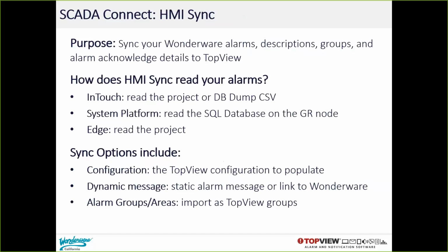The next step is to sync your Wonderware alarm to TopView. This step configures your alarms, alarm acknowledgements, alarm descriptions, and groups or areas for use by the TopView engine. The method used for syncing alarms depends on the Wonderware software. For InTouch, we can read the InTouch project or parse a dbdump CSV file. For System Platform, we read the alarms from the Galaxy repository database. And for InTouch Edge, we can read your alarms from the Edge project. The sync contains a few options that let you control some of the syncing details. For example, do you want to import the existing groups or areas from the SCADA system into TopView as TopView groups?